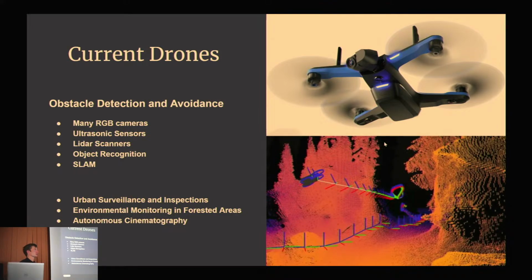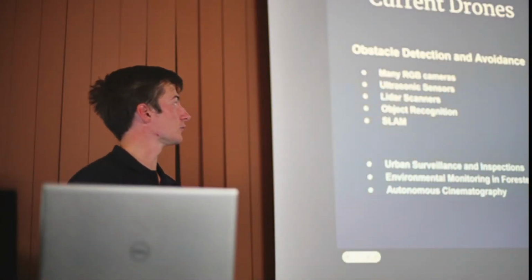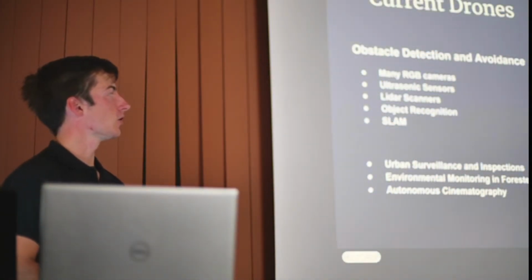Basically, the Skydio drone, back in 2018, was the first available commercial drone which had implemented object avoidance. But there was a catch to it. The drone was able to operate only at a maximal speed of 5 meters per second, and it was due to the reaction time of the sensors that were able to catch any obstacle from 15 meters. If, for example, the drone could go much faster, it would crash before it could detect that there is anything in front of it. That's why companies like Skydio switched to onboard camera feed.